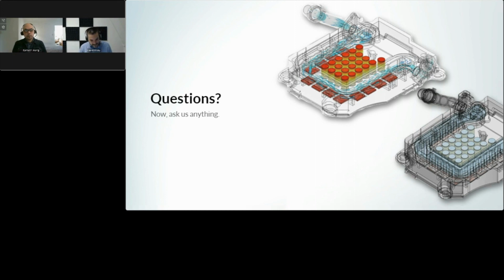And so that's why, yes, the upload is associative, meaning you can bring in a new version of your CAD model. Of course, if you bring in a completely new model that has nothing to do with the version before, SimScale's associative update will not pick this up. But if the version is close and specifically from the same CAD system, ideally if the CAD system preserves IDs over topological changes, then you can simply swap the geometry within SimScale, and all boundary condition assignments, mesh refinements, etc., are preserved.